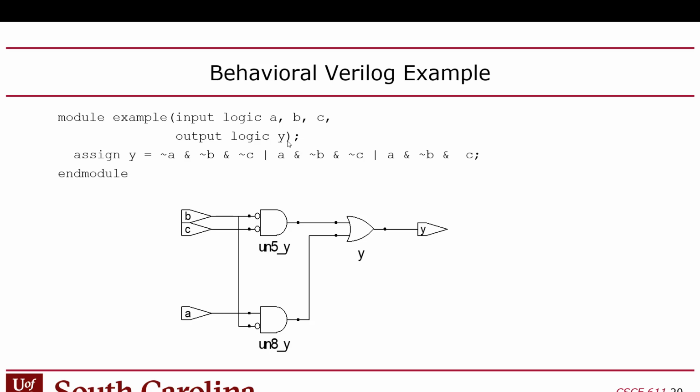Why is that? Logically equivalent. Yeah, exactly. So this is logically equivalent to what's written there. It's not a direct mapping. So when you guys took 211, you might have minimized that, but whenever you went from logic to gates, you would have done a direct translation, right? Whereas you'll notice that the tool here is doing a logic minimization and coming up with, I don't know by what standard that's optimal. I don't know, number of gates or delay or power, whatever the objective is, it tailored this implementation of this equivalent circuit to meet that objective, right?